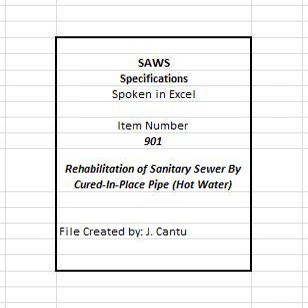2. Hydraulic capacity. The contractor shall submit design calculations verifying that the CIPP shall have flow capacity equal to at least 100% of the existing pipe. Flow capacity calculation shall be based on Manning's formula using N, Manning's roughness coefficient, of 0.013 for existing sewer. The N value for CIPP used shall have been verified by an independent testing laboratory, third-party testing, which the contractor shall provide.